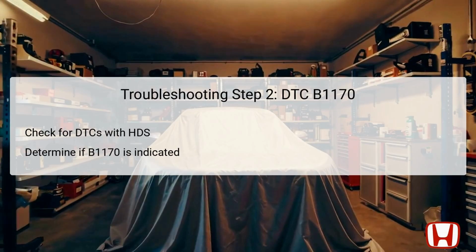In this case, the system could be functioning correctly at that moment, but the technician should still inspect for loose or poor connections between the gauge control module and the VSA or ABS modulator control units. Identifying intermittent issues can often be more challenging than persistent ones. Therefore, vigilance during this step is critical for effective troubleshooting.